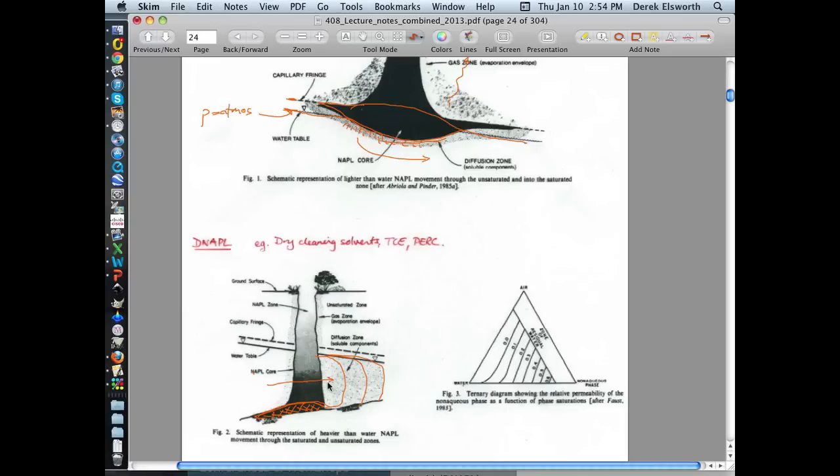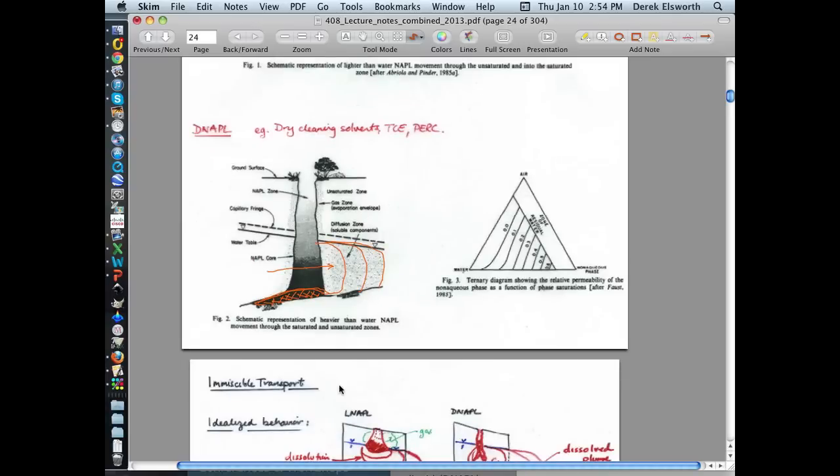And the reality is that if you don't take out the source material, which is often a preferred reason of remediation, is to not remove the source material. But if you don't remove the source material, you'll be remediating it forever, because basically these components are toxic of the order of parts per billion, and you can certainly supply parts per billion from a very small volume of material for a very long time to come in a reservoir or an aquifer where you have decent flow rates.